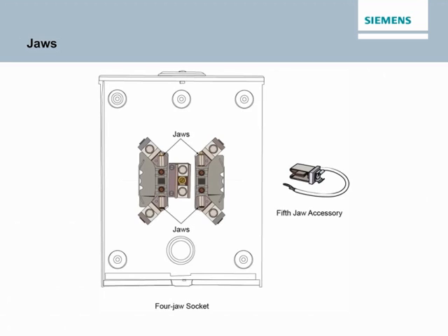After the line, load, neutral, and ground connectors are installed, the meter can be plugged in. A watt-hour meter has 4 blades that plug into the jaws of the meter socket. Once installed, the meter completes the circuit by providing a path for current from the line to the load.